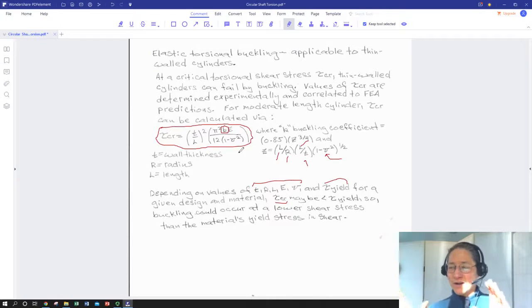So those are the trade-off points that will give you a design envelope that is bounded when we're looking at our shape. And of course, on the nice side, stiffer materials, bigger G's, bigger E's, are going to be in your favor, both from a buckling and a max deflection standpoint.